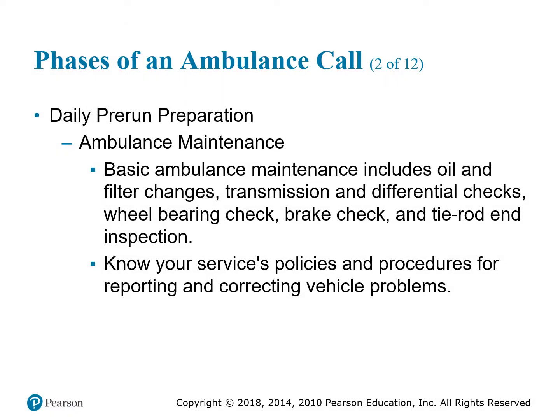Daily pre-run preparations: ambulance maintenance. Basic ambulance maintenance includes oil and filter changes, transmission and differential checks, wheel bearing check, brake check, tie rod and other inspections. Know your service policies and procedures for reporting and correcting vehicle problems.